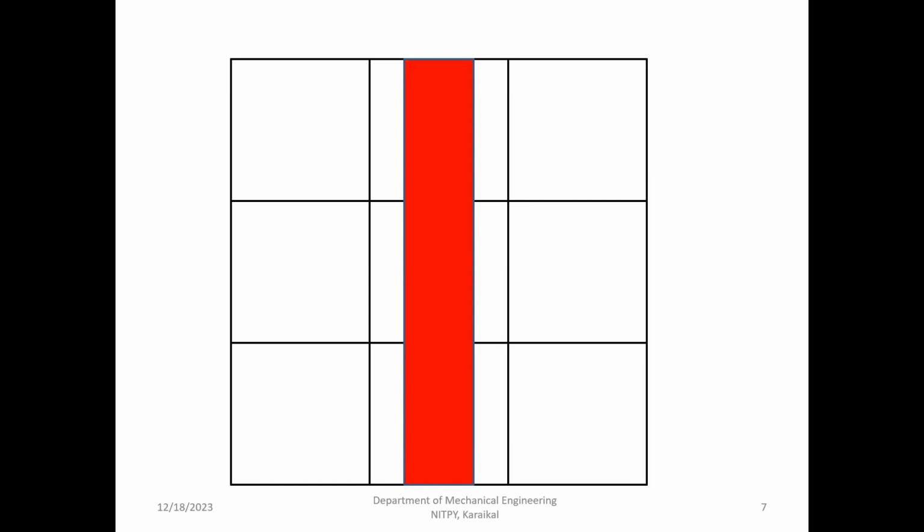That is the reason commercial software, if you are going to go with fluid flow problems, you'll be going with a finite volume method rather than the finite difference method. It's not that finite difference will not be able to solve this. Finite difference also can solve this. But the amount of programming still required will be a little bit on the higher end. So we'll be mainly going with the finite volume method to calculate this.